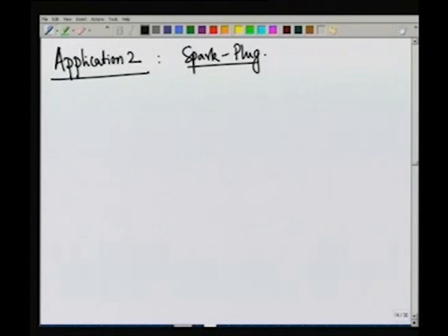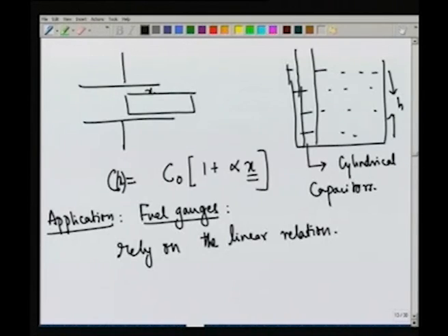Okay. One statement that perhaps I should make before I proceed is that what the manufacturer does is actually to calibrate. So, he keeps on measuring capacitance because there are all kinds of corrections, finite length, finite size, etc. So, he calibrates H against capacitance, draws a line which need not exactly be C naught alpha, and with this calibration the needle is made to show that particular reading.